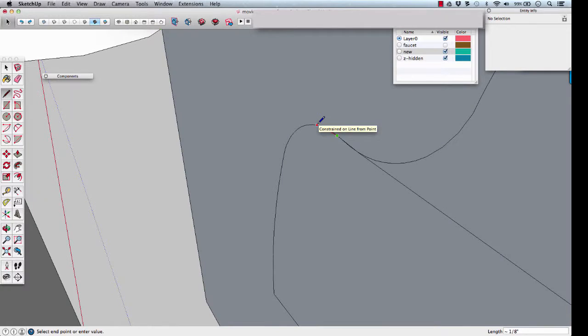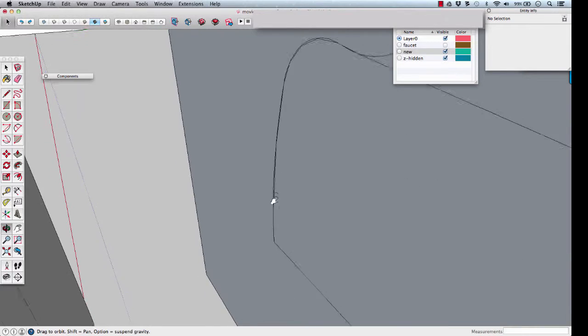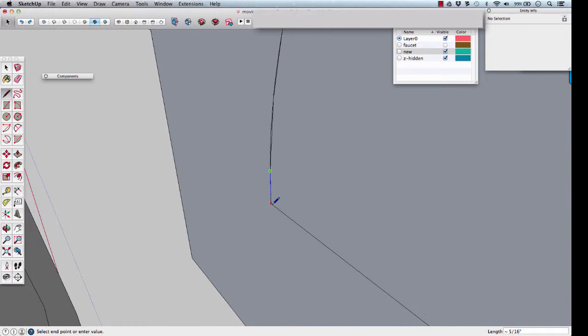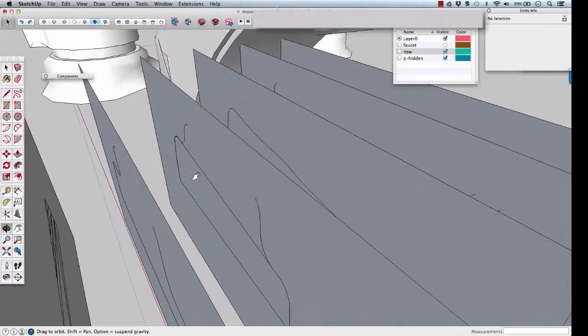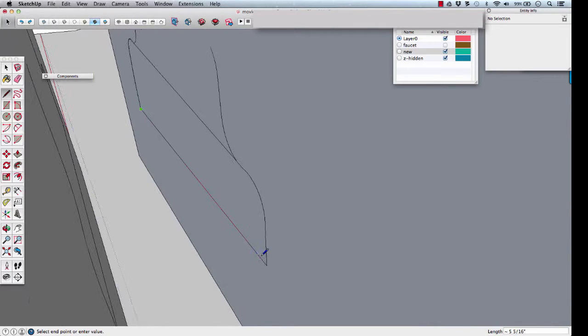There. We could do an arc. A. We'll make a 4-point arc, 4S, 4-segment arc. Come down. There's 4 segments. Even found the tangency. Do a line, L. Maybe we'll put a couple in here. There's a slight curve in the back, but we're going to simplify it way down. Touch the base. It's a little hard to fit inside there, but we'll do it. Come up.